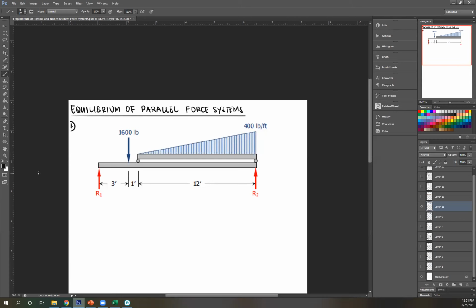So when you have something like this, you have 2 beams on top of each other. Right? You're going to work on 1 beam at a time, starting with the beam with the least reactions, or the outermost beam, which is in this case, the one carrying your distributed load. So let's create a free body diagram of that. You have this, you have your load, 400 pounds per foot. And then you have these objects.